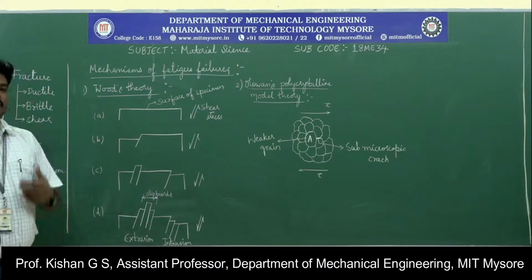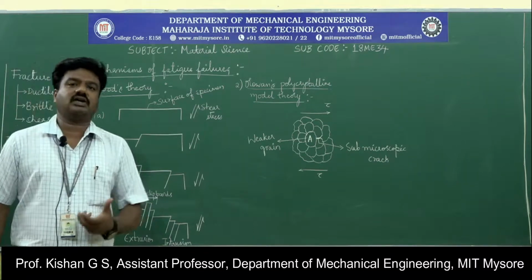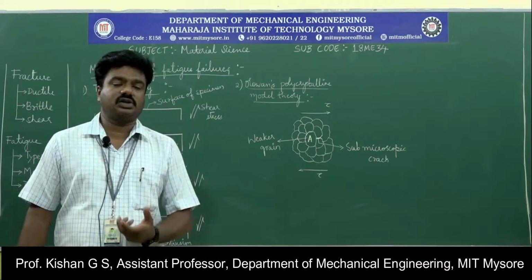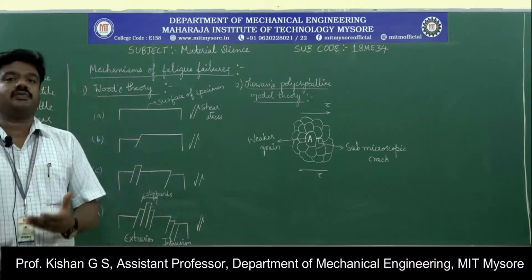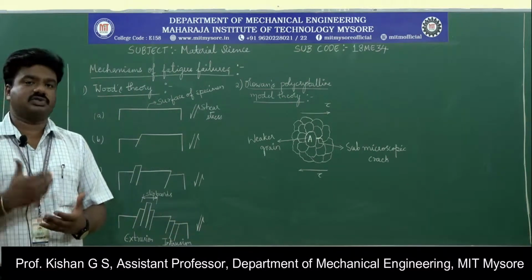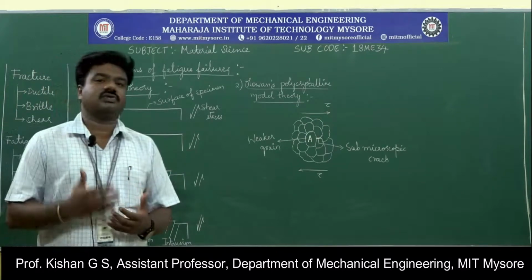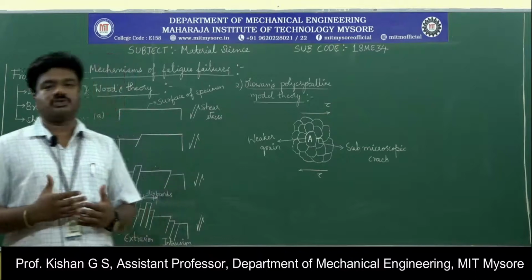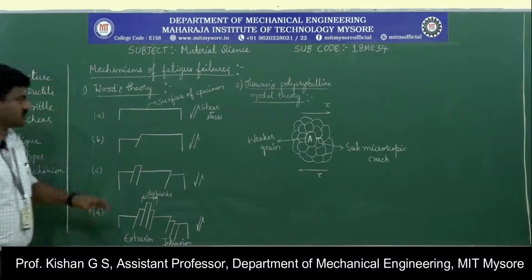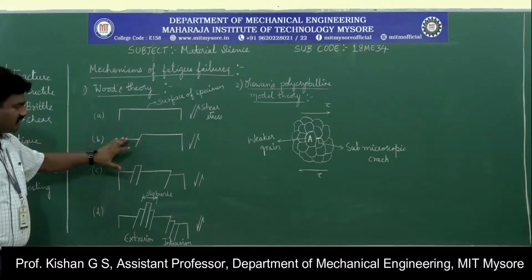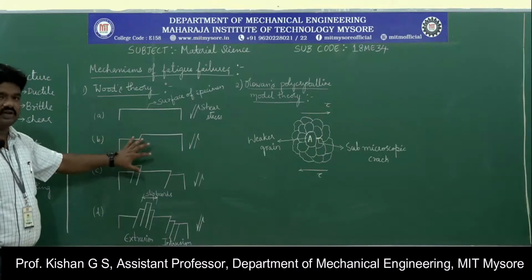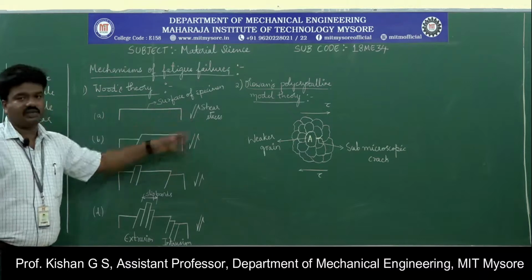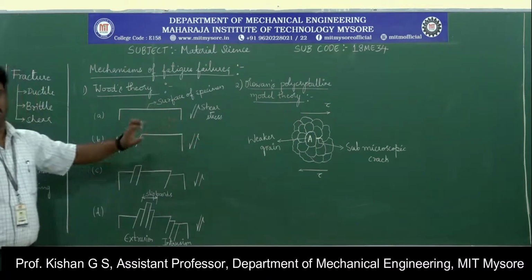When we alternately apply the load on either side, that leads to a shear condition, and there will always be movement of slip even in the opposite direction. That means along the direction of loading over the specimen, the slip will always try to move in the opposite direction. So you can observe here we have identified a formation of slip over a material subjected to alternate loading, which can be generally defined under shear stress loading.